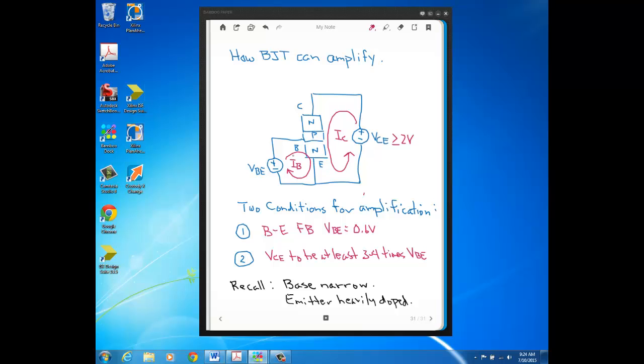Because now if I connect this transistor up into a circuit with resistors and say some signal that I want to amplify, like some sort of AC signal, well, if I make the base the input to that circuit and I make the collector the output of that circuit, well, having a much larger current at the collector, the output of the circuit, compared to the base, the input of the circuit, I can get a bigger voltage signal at the output of this circuit compared to the voltage at the input of this circuit.